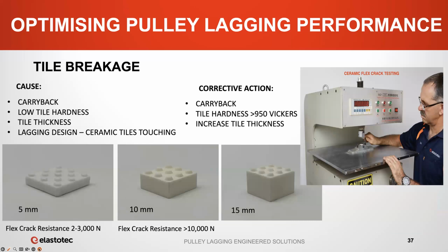Now, there are some things that we can do to resist the breakage or cracking of tiles. And tile thickness is a way of increasing the resistance to breakage. We use a machine called a flex crack tester, which measures the force to break a tile.